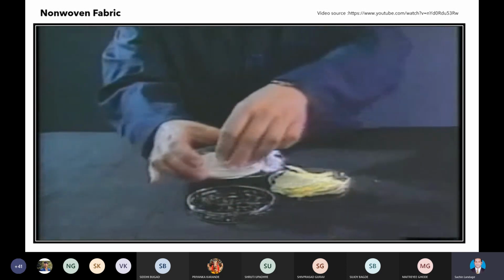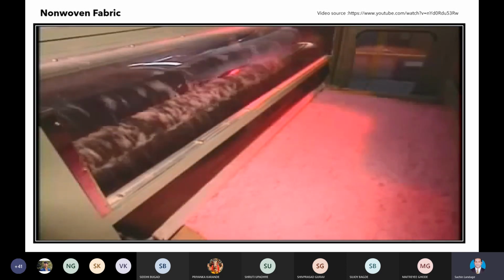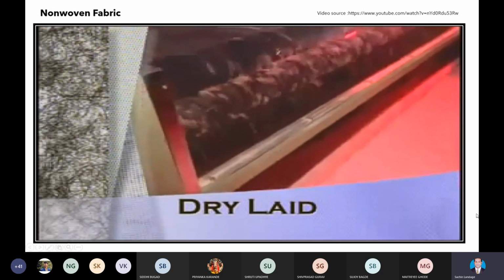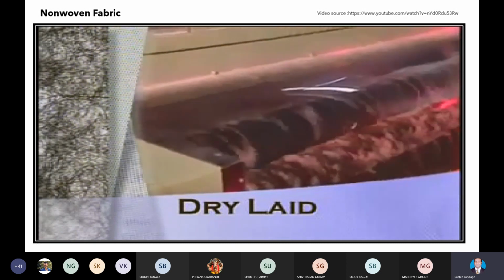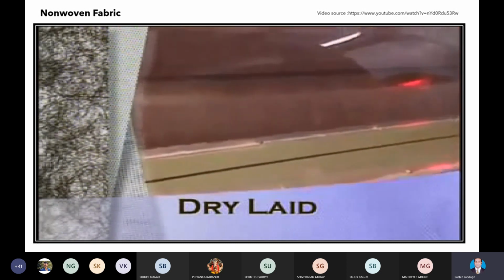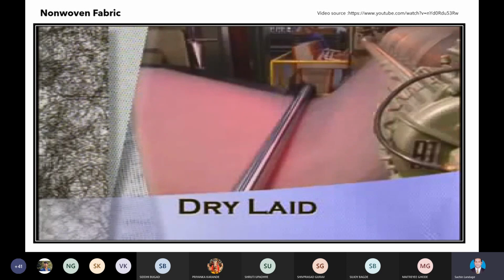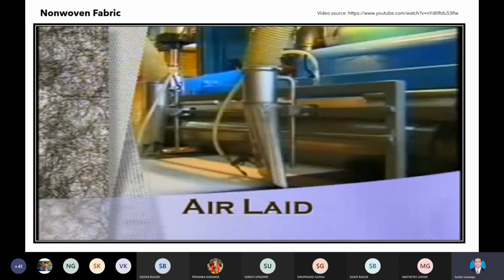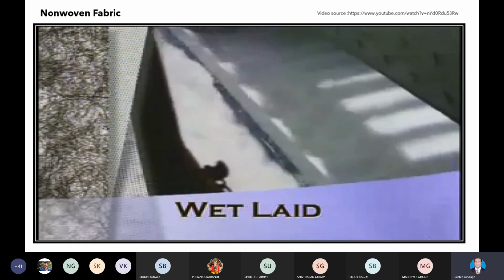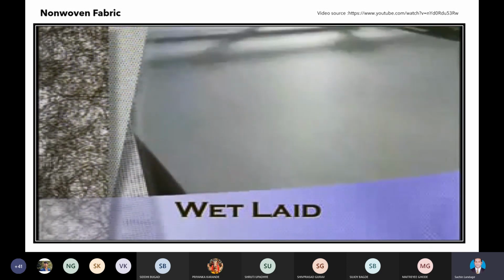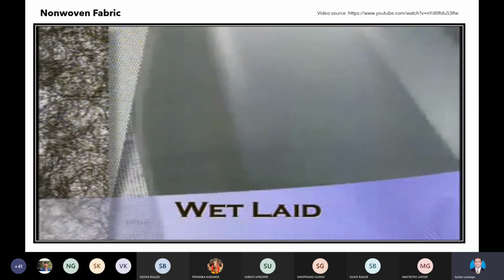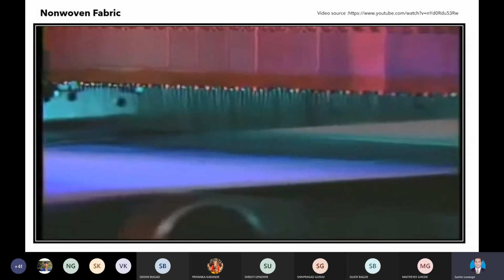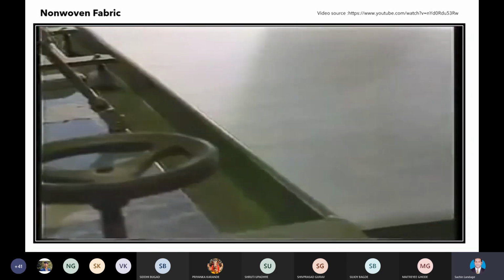All these capabilities are carefully engineered into each fabric using a range of natural and synthetic materials and various bonding techniques. Non-wovens begin as loose web mattings that can be formed through several processes. In the dry-laid process, fibers are mechanically combed or carded into position, or laid down by a controlled airstream. Or they can be transported by water, the wet-laid process. Then, the fibers are joined together by resin or fused by heat.